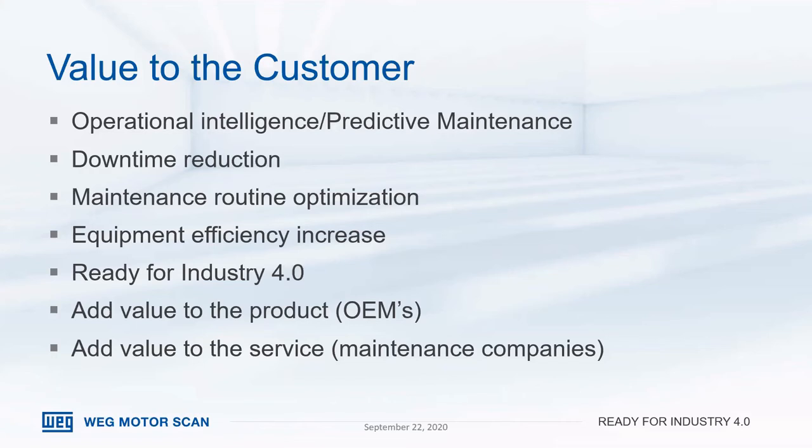And when you get into the midstream market, you've got a lot of areas where there are potentially hazardous explosive areas. So the motor has to be what we would call Division 1 or Division 2, UL or CSA classified. So you get into all those kinds of things too, the nitty-gritty details on the environment. And then the third really is, okay, well, once you get the thing, you've got to maintain it and make sure that it's running properly.